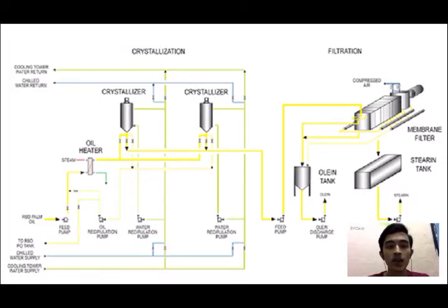This technique is called fractional crystallization and used to obtain oil or fats more suitable, for example, as cooking oil or for margarine and shortening production, through continuous crystallization of the oil in a solvent followed by separation of the liquid and solid fraction through a continuous drum filter.